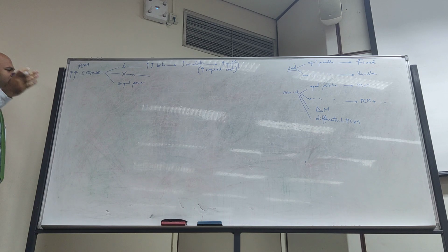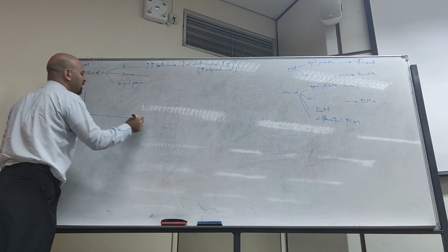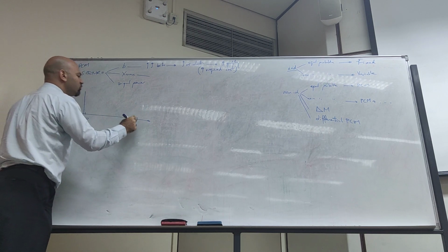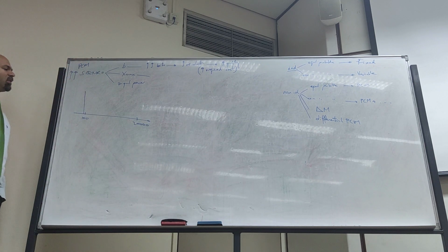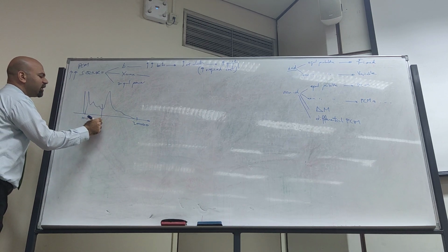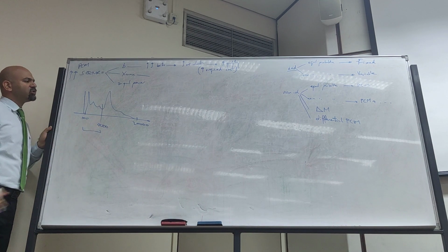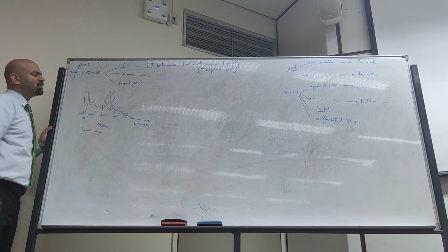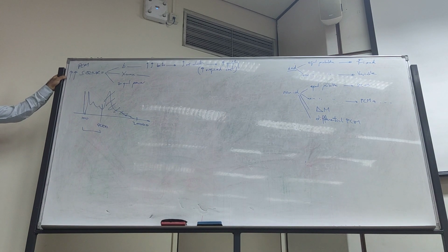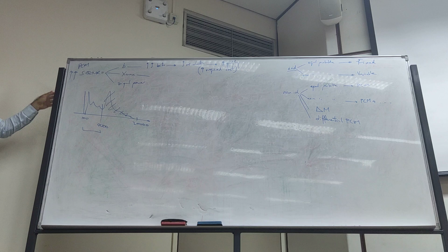And a similar idea, last time I think I explained about DFT and these. Whenever we have a voice signal, for example, it's from 100 to 20,000 as a bandwidth, and this is the signal. They decided to cut the signal and make it at 4,000 or 3,500, depending on the standard. Why did they do that? They decreased the range. By decreasing the range, it becomes more suitable, and they found that the amount of data up here is about 5%, which we can neglect. So decreasing the range is like concentrating whatever you have there.